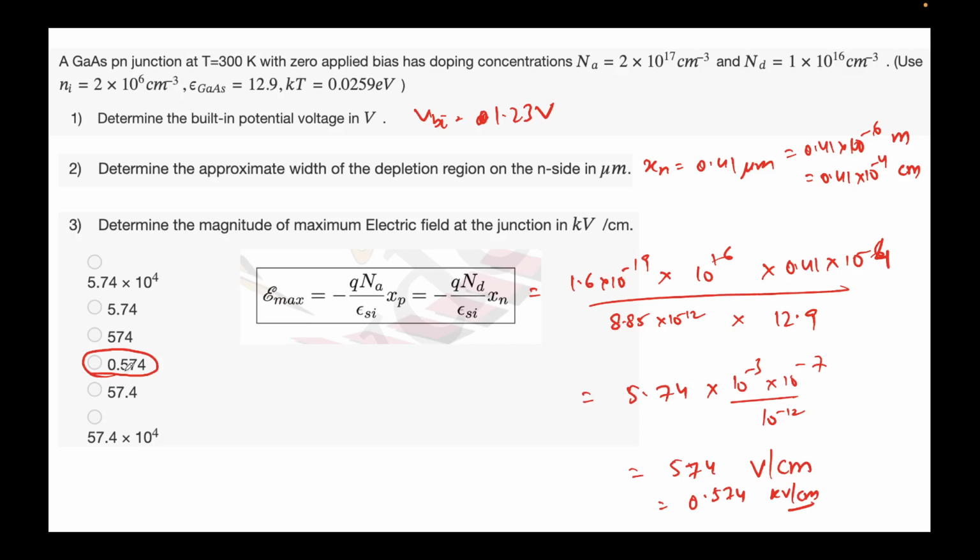So from this problem of gallium arsenide, we learned a few things. First, you need to ensure that it's a PN junction, abrupt junction, only then these formulas are applicable. Second, you can also check whether it's an abrupt junction or not. If it's an abrupt junction, life becomes much simpler, as we see that in this case it's a P plus N junction. If it's a P plus N junction, then all your electric field, all your depletion width is going to be in the low doped region. In this case, in ND, we saw 95% of it was there.